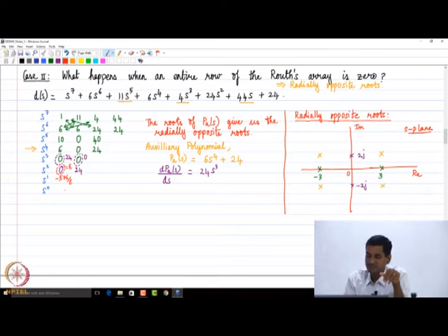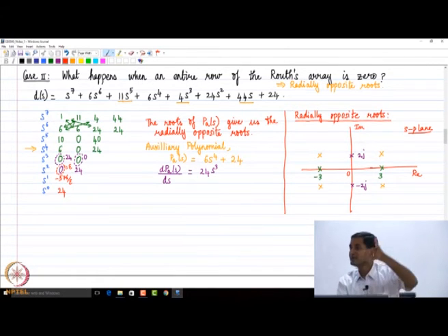If I come to the s power 0 row, what am I going to get? I will just get 24. I have completed the construction of the first Routh array. Now I look at the first column. If you look at the element above and below epsilon, what can you tell about their signs? The element above epsilon is 24, the element below epsilon is going to be negative in sign. Minus 576 by epsilon is going to be negative. So do you think there is a sign change above and below epsilon? That implies that there are roots in the right half plane.